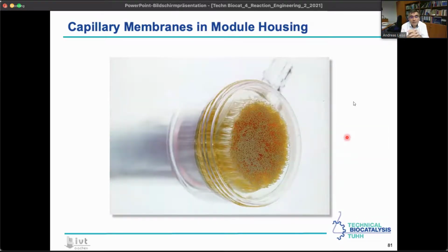For scaling, other devices are used. What you can see here is a capillary membrane. You can imagine it like spaghetti noodles standing in a glass. That's the same: this is the glass, and these are the noodles. These are the hollow fiber membranes, and the trick is they're glued in at this top and also on the other side. Through the membranes, entering on this side, we have the retentate, and on the outside, where you see the outlet, flowing around the membrane, that is the permeate.